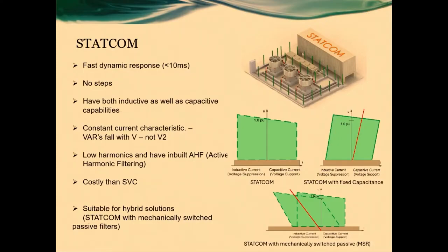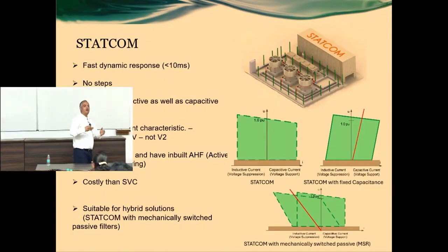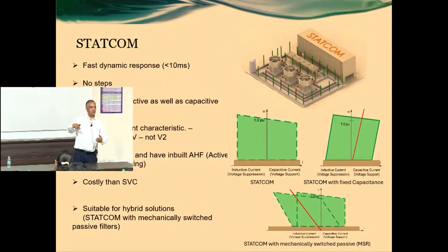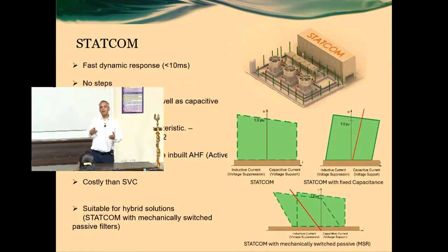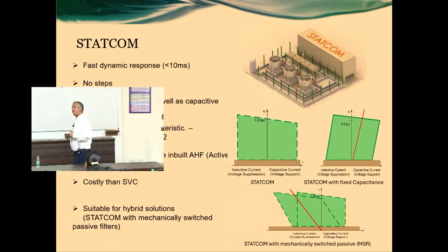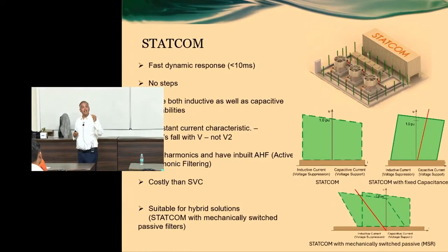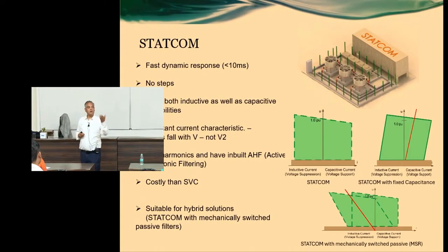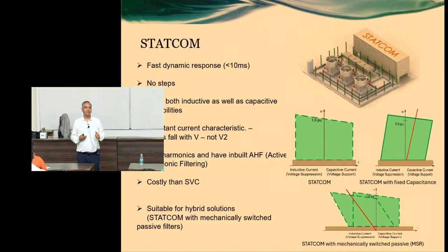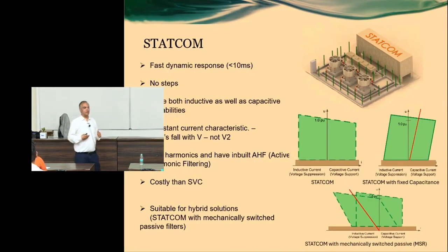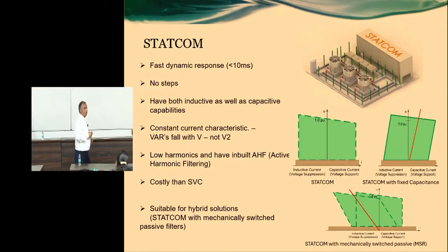So now coming to STATCOM. STATCOM has the option, you know, the limitation of previous devices like that. Their compensation capability was going to be compromised when you are moving away from the rated point value. But here, the amount of active current or reactive current to be injected is almost constant irrespective of the deviation in voltage. So that's why the STATCOMs are more powerful.